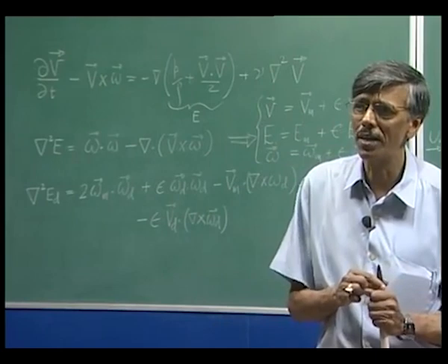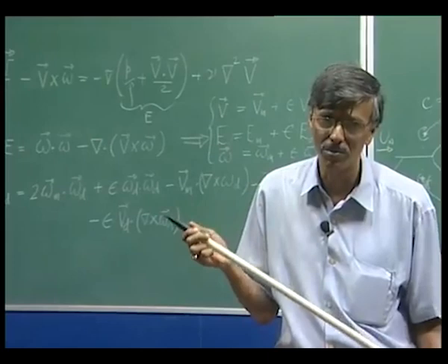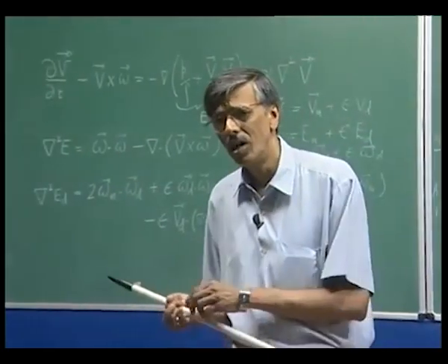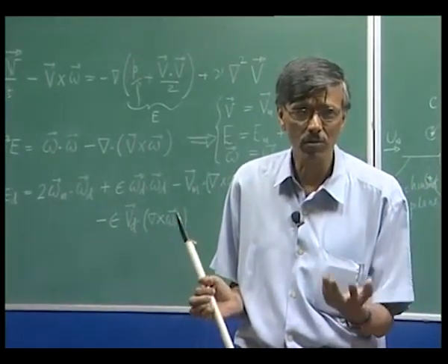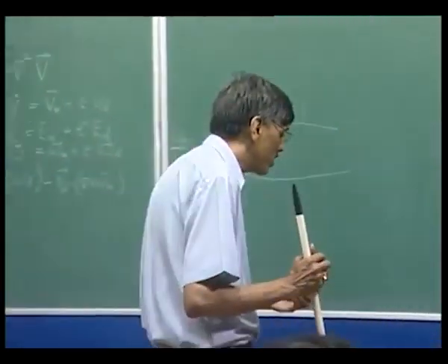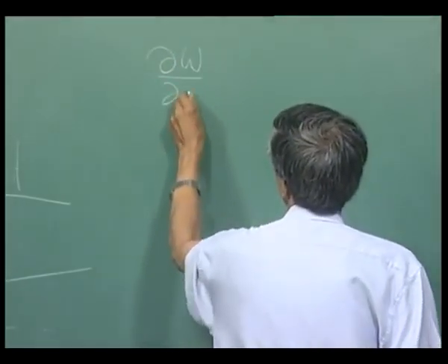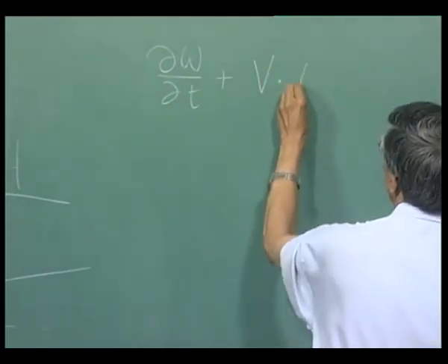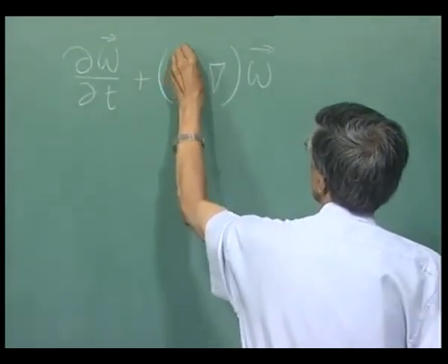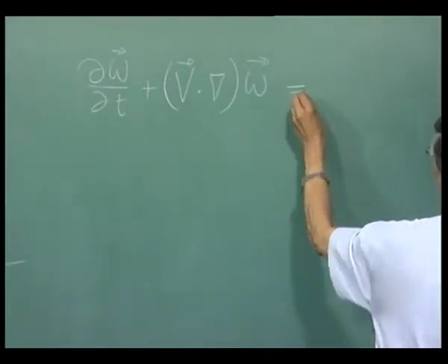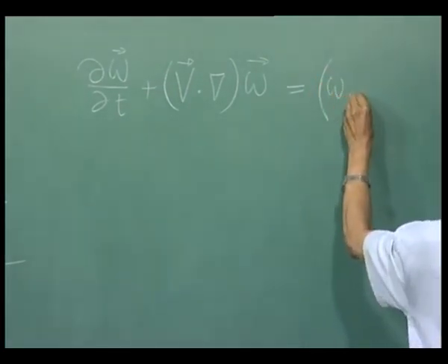See, this was also another thing that we have noted that for a long time the discussion in fully developed turbulent flow has remained with the writing of the vorticity transport equation for general flow field, and that vorticity transport equation looks like this. We have this term plus V dot del, the vorticity, and on this side we have the vortex stretching term, omega dot del.